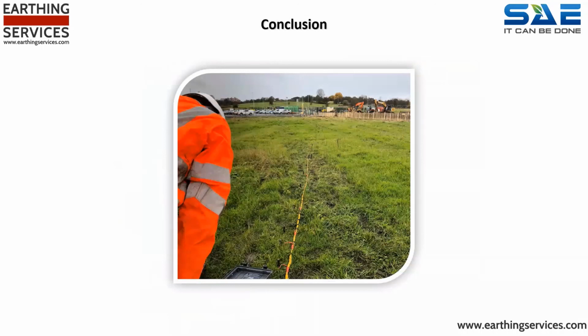When it comes to electrical earthing systems, there are several factors which will determine how well it works, being the resistance of surrounding mass of earth, i.e. how well it discharges electricity; the inherent resistance of the conductors, i.e. how well the conductors discharge electricity into that surrounding mass of earth; the contact surface area of the conductors, i.e. how much conductor interfaces with the surrounding mass of earth; the total discharge zone of conductors, i.e. what's the footprint of the conductor network; and the resilience and longevity of the conductor network, i.e. how reliable is that conductor network on an immediate and long-term timescale, meaning the conductors work today, will they tomorrow, will they in a decade, and so on.